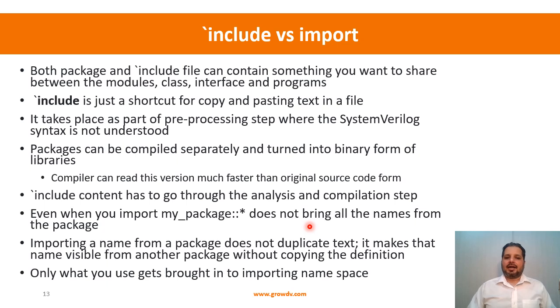And the other thing is that when you import something from the package, it does not duplicate anything. Okay, so it's still a unique thing that remains. It remains as one entity, one variable, whereas when you do the tick include, it duplicates it in every place where you do the tick include. So that is the difference between your tick include and import.